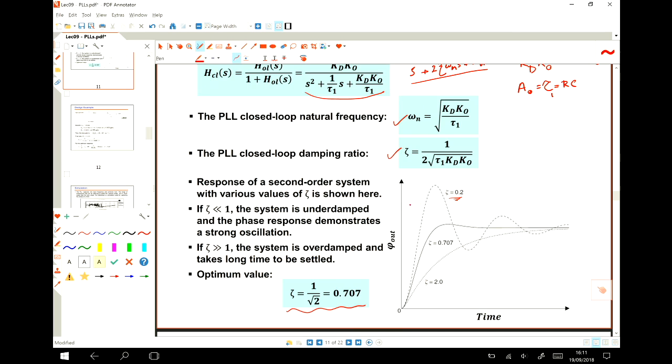And if our phase margin is like this, then maybe when we are trying to get locked, at this point we go out of the lock region, and everything starts again from the beginning and it doesn't work. We can never get locked. Or if we use this one, then instead of getting locked in, say, 100 microseconds, maybe it takes 10 milliseconds to get locked.